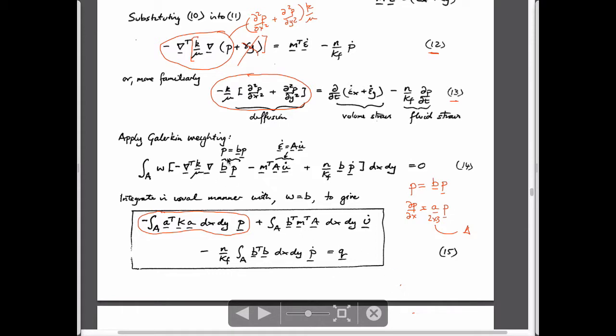So what's next? So this is second order. What is this? This is 0 in space, but first order in time. So 0th order in space is going to be, actually we can't quite do it, can we? Because it's actually first order in space, so it's not 0th order, right? Epsilon x is equal to change in displacement with location, so it's actually not 0th order, it's first order in space. And so first order in space, as we know, is shape functions, this matrix, and A.